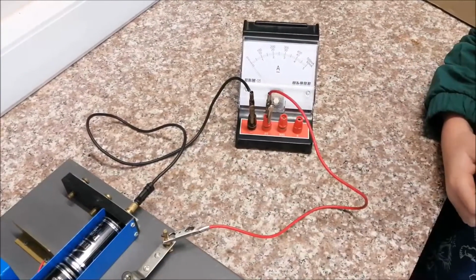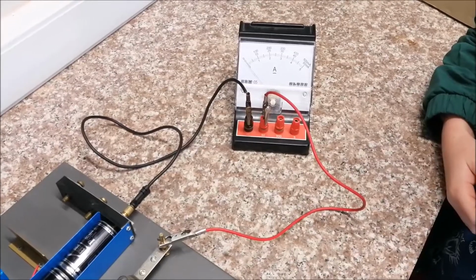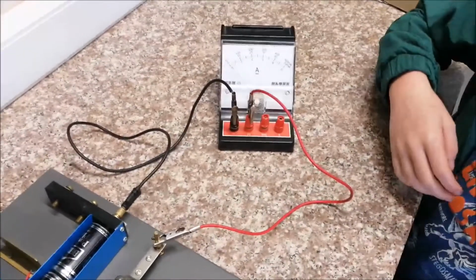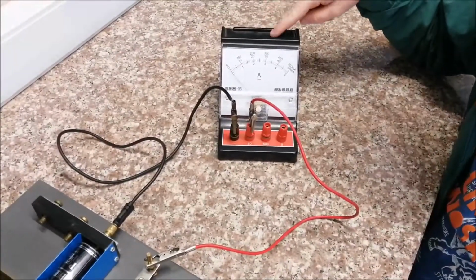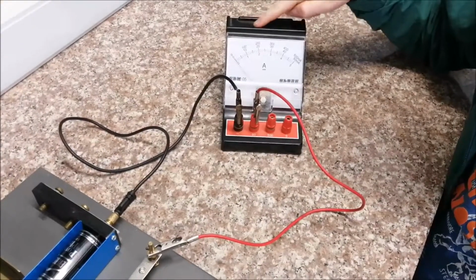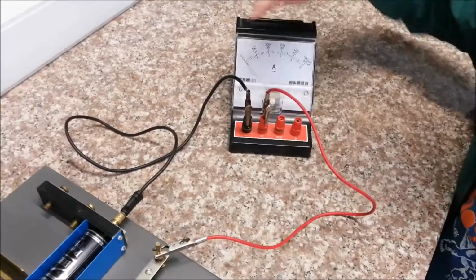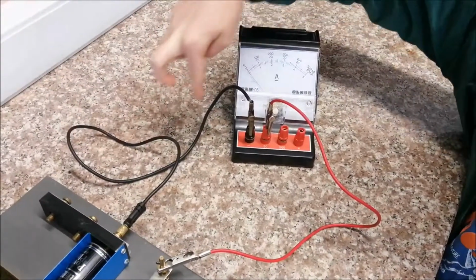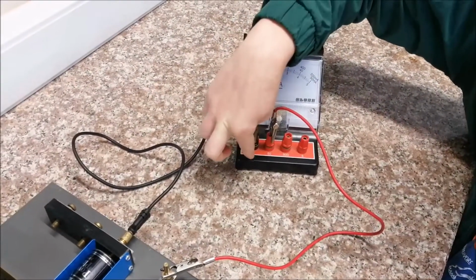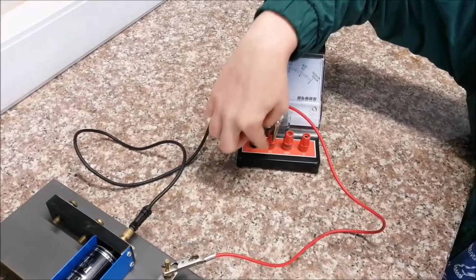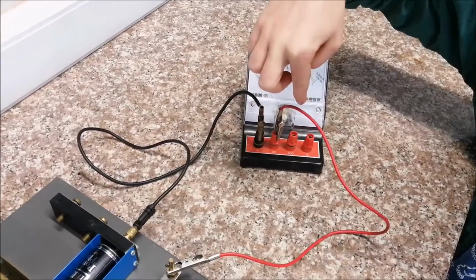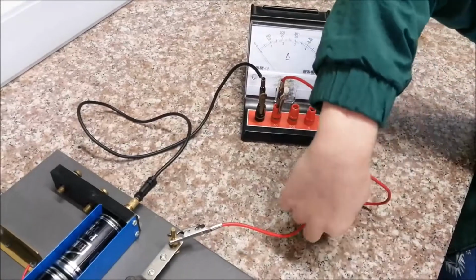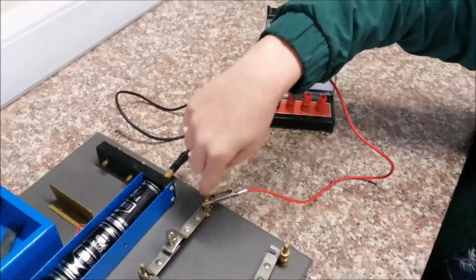Okay, so we want to first of all connect the ammeter in series. So that means that we want all of the electrical current to go through the ammeter. So you can see the black lead is exiting the battery, and the current flows, as we are pointing now, into the ammeter. So all of the current that comes out of the power source will go through the ammeter and then out of the red lead, and it will join our circuit that we have started to create.